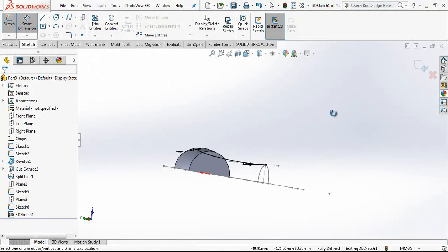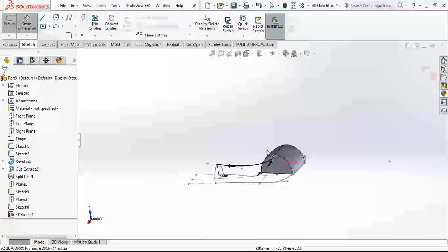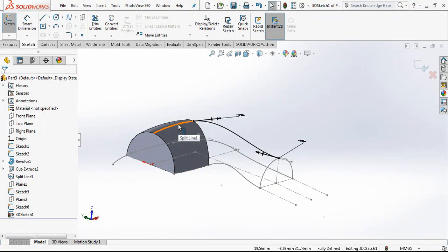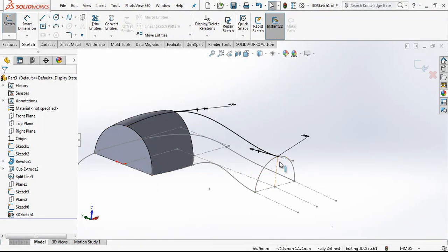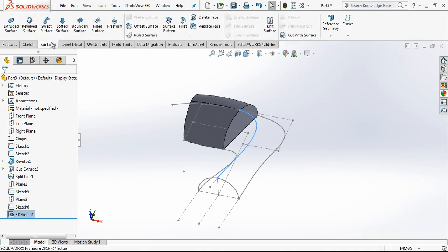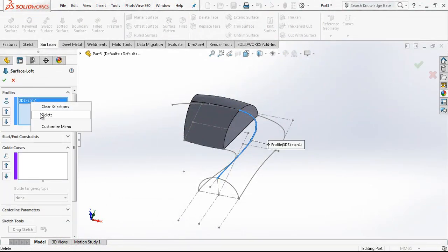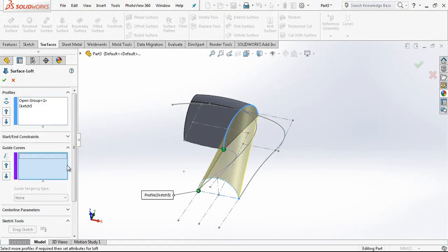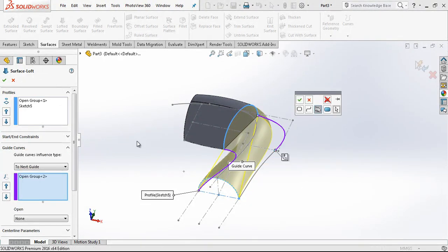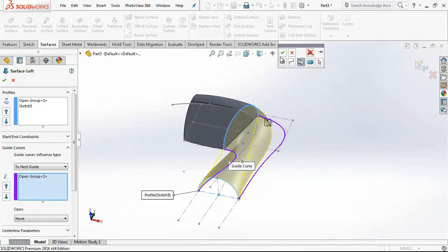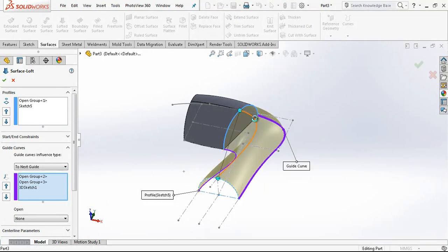And I create here a 3D spline on the area, like a bridge spline, from this point to this point, and I use two objects out of this spline to handle that. After this point, guys, we just create a lofted surface, and the first loft profile will be this, the second this, and now we give our guide curves, and this consists of two curves. That's why I'm choosing in two steps, and my last guide curve.